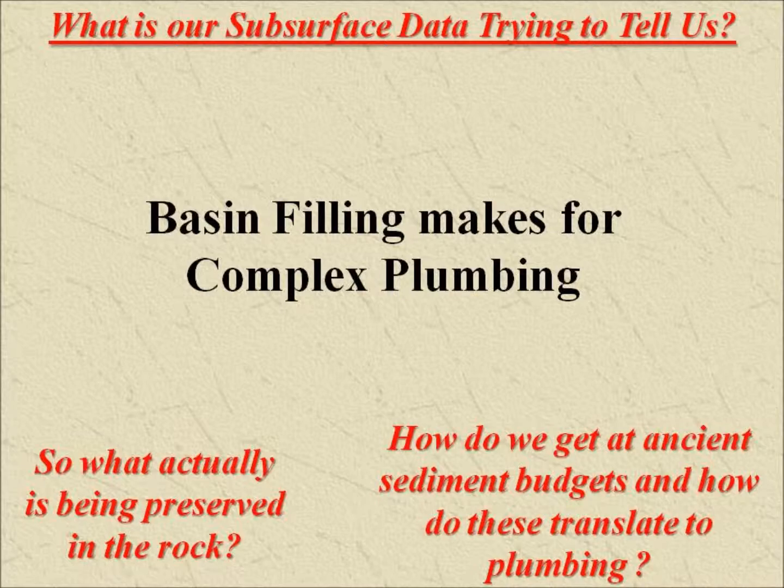But John, the way I understood yesterday is that at the beginning of time, when all the water is at the same temperature, it's not a problem. But once you start circulating, residence time in order to heat that water to the appropriate temperature is crucial. So, based on what you just said, when you have channels, when you have potential for bypass, understanding where this water flows in order to maximize the residence time is quite important.